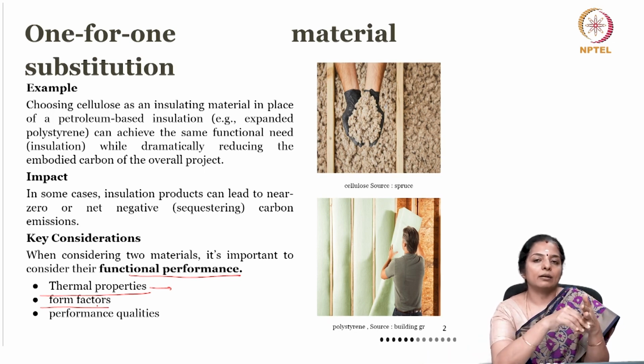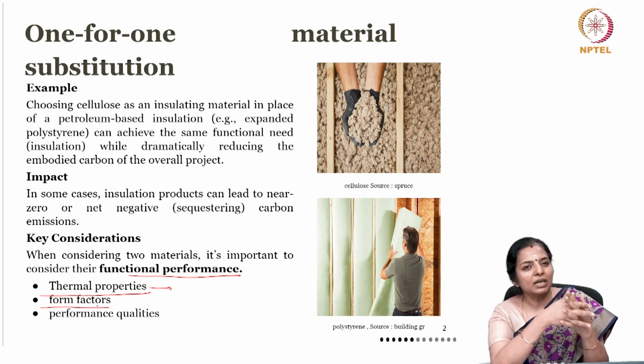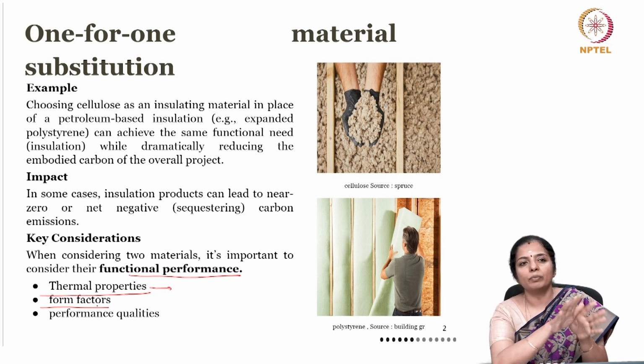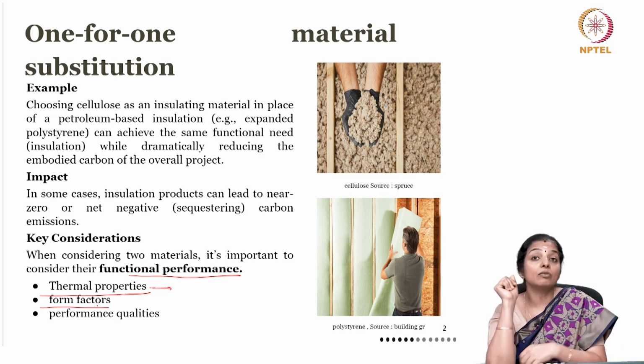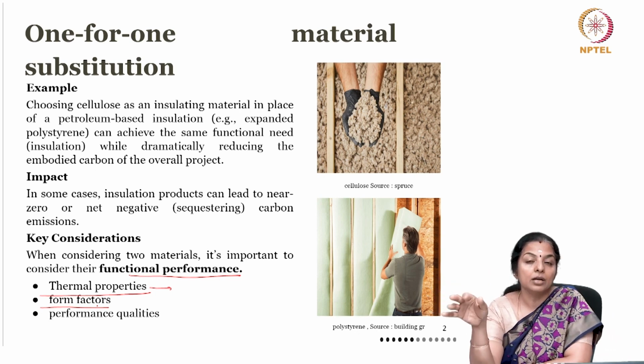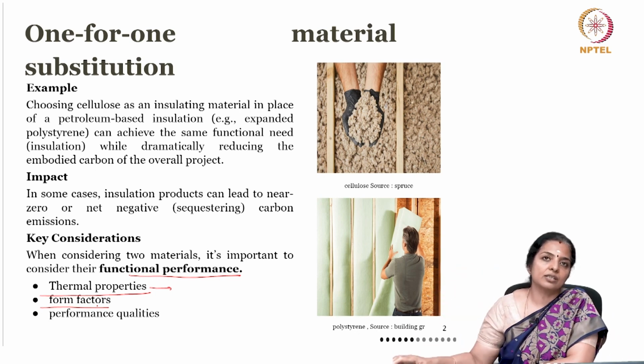Because you also need to look at its maintenance. When I say performance qualities, it's not necessarily from a thermal performance point of view, but from the point of view of maintenance. Sometimes it becomes very cumbersome and difficult for us to keep replacing that particular material. Just because it's low embodied carbon, you use it, and then it becomes cumbersome. What will happen is, over a period of time, you'll be so fed up, you will end up putting another conventional material which will be high embodied carbon.